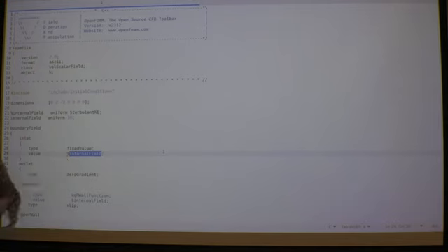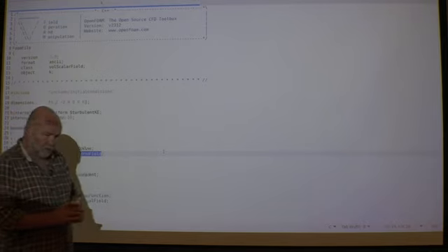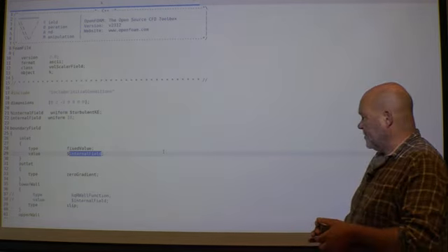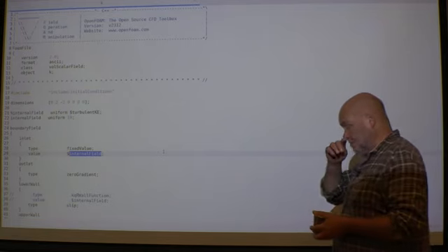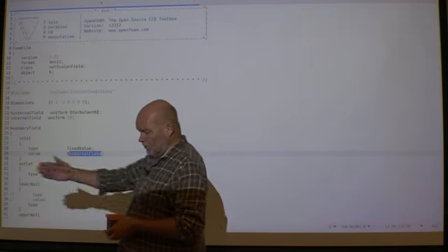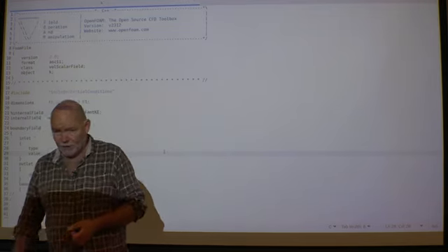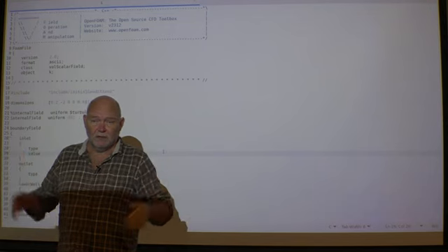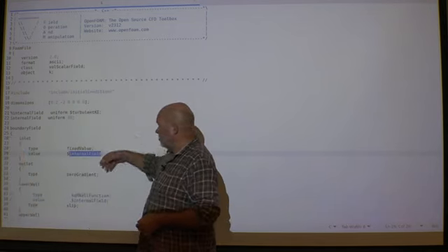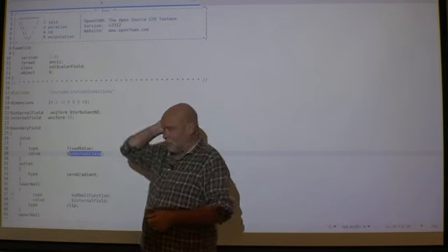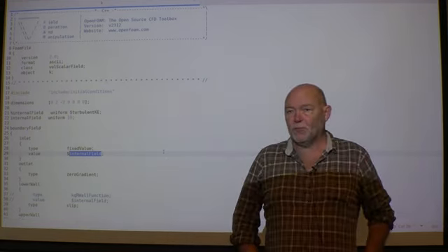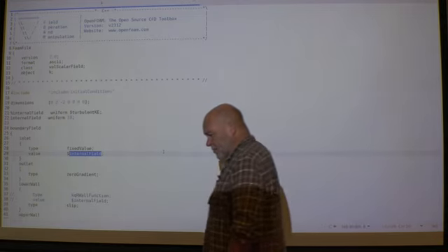Meaning, what should you put in? For K, epsilon, omega, whatever model you choose, you have to put in something as a boundary condition. But remember the problem. This car is supposed to move forward at a given speed, but the air it's hitting should actually be still. So actually, it should be 0. But now these turbulence models, they don't like it when things are 0. So I would suggest you just put in a very small number and see what happens.